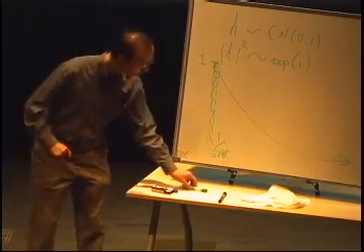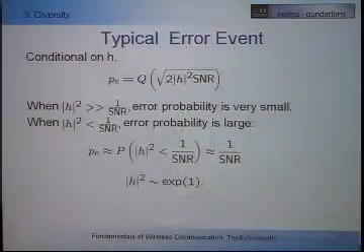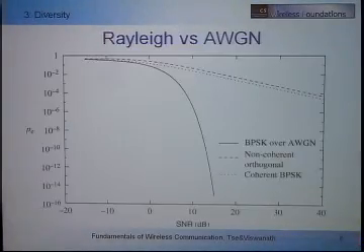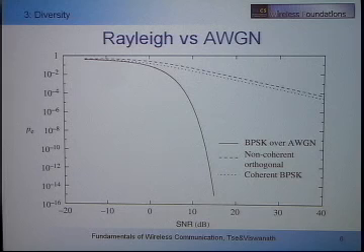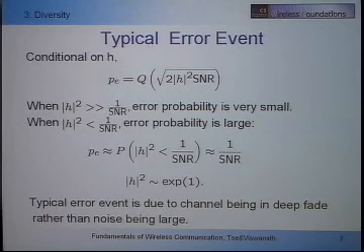That's why. Now, why am I keep on focusing on high SNR here? High SNR means, 15, 20 dB, this kind of range. Well, for this particular problem, there's no point in focusing on low SNR. Because low SNR means your error probability sucks. Okay? So we'll come back to low SNR later on when we have enough tools. But for this particular example, high SNR is the right thing to focus on. Okay? So high SNR means that your error probability is of the order of 1 over SNR only.